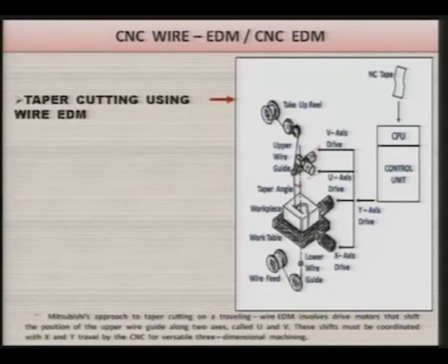As you can see here, I have marked it. These shifts must be coordinated with X and Y travel by CNC for versatile 3-dimensional cutting. So, this particular version of the CNC wire EDM process is useful for cutting 3-dimensional components.